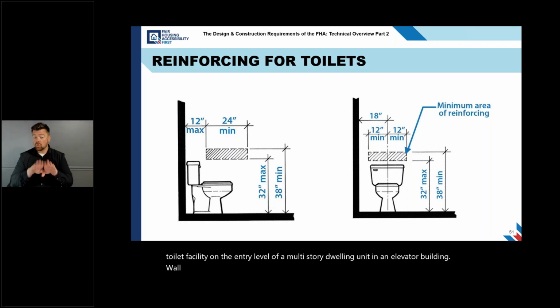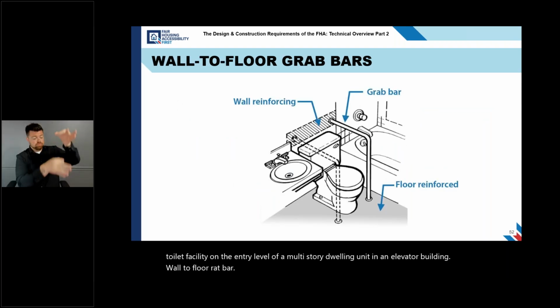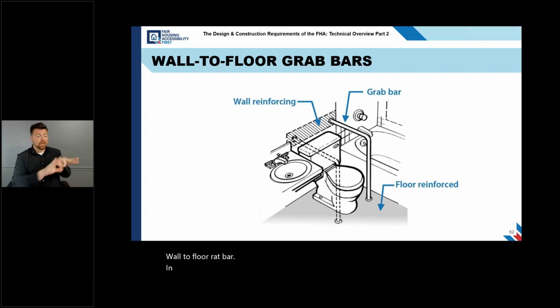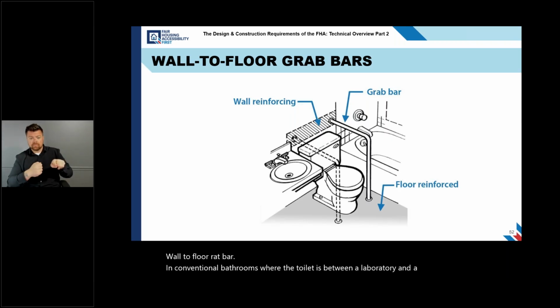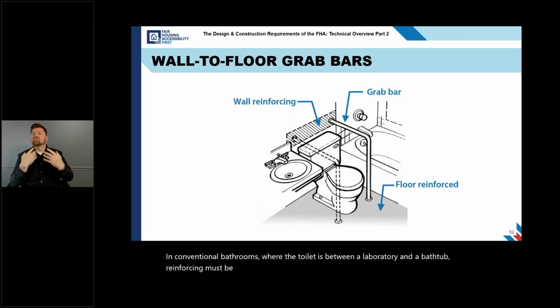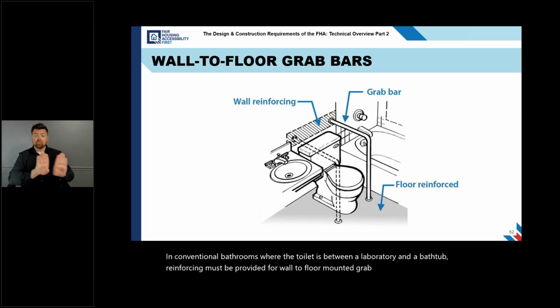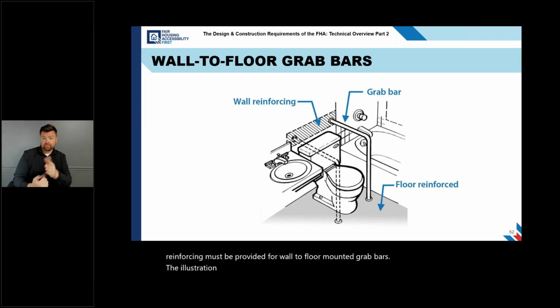Wall-to-floor grab bars. In conventional bathrooms, where the toilet is between a lavatory and a bathtub, reinforcing must be provided for wall-to-floor mounted grab bars. The illustration shows areas that must be reinforced for a wall-to-floor mounted grab bar.